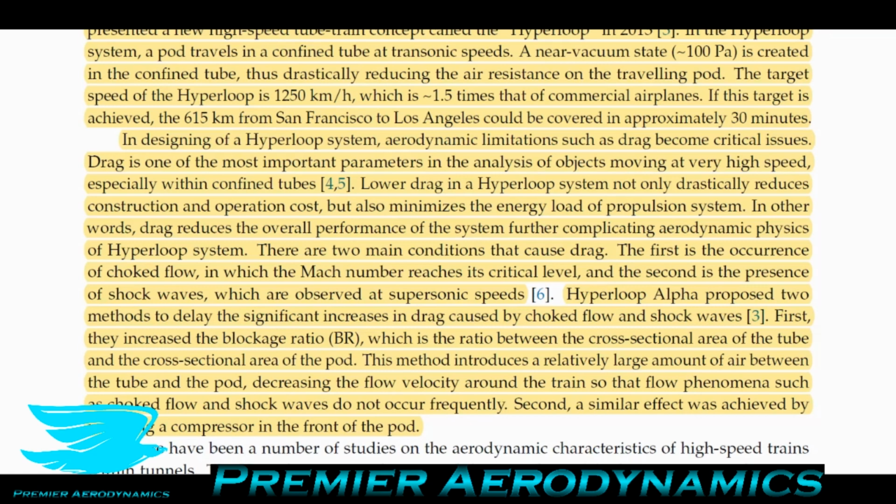And the reason why is because if you think of, let's say, an airfoil, if you've ever studied airfoils, you know that over the top of an airfoil, the flow accelerates. And that's because it's a slightly curved surface, or however curved it is. So even though you might have a free stream velocity of, let's say, a Mach number of 0.9, because the flow has to accelerate over the surface of the airfoil, it will hit 1. And that's when you get sonic flow. So that means the critical Mach number is actually 0.9, because that's the free stream velocity at which you'll start getting sonic flow over your object. So that's what they mean here by this critical level for the Mach number.